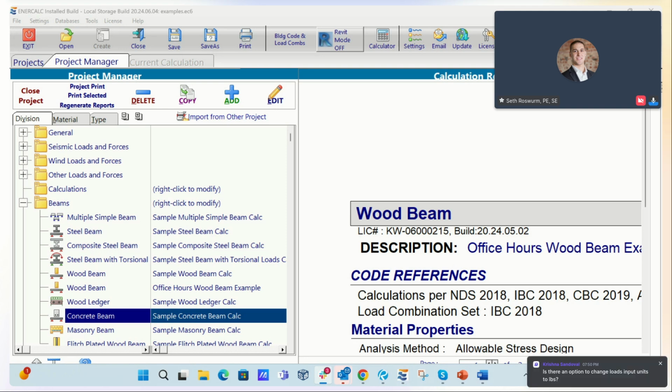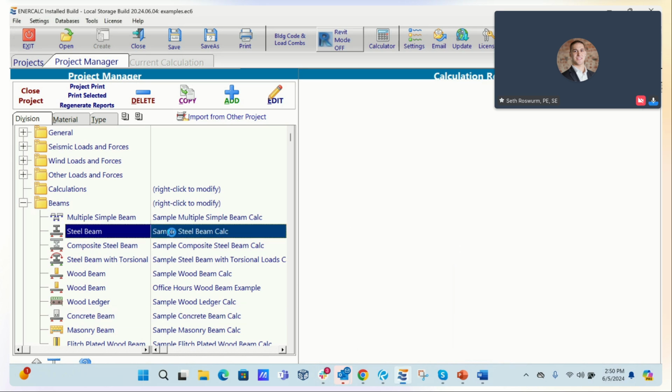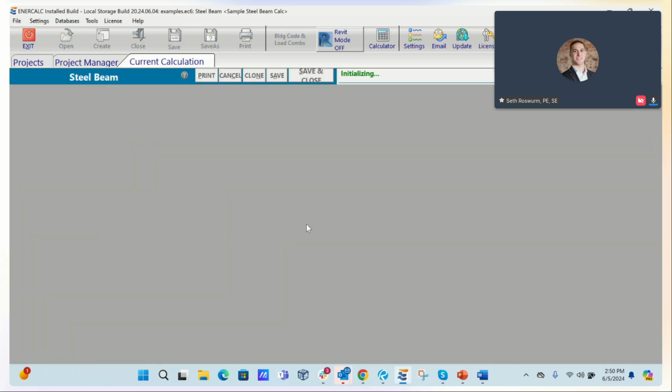All right, so we had another question. This is from Shaylin, and this one's kind of a long one, but I'll read through it here. If you have a high wind load where you have overall uplift for a load combination, talking about load reversal on wood beams, and this is similar to the discussions we've had in the past about load reversal on a steel beam, whether that be a wind uplift condition, whether it be a multi-span or a backspan and cantilever condition where you get load reversal, talking about the flange bracing conditions, compression side of the member, and then that load reversal, you get a reversal of the flange bracing.